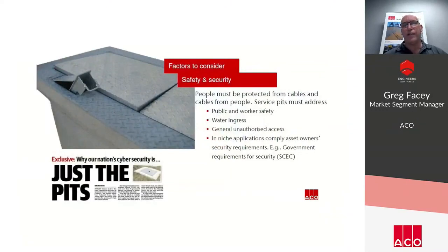We also need to consider the safety and security requirements of the cable enclosure, because people must be protected from cables and cables protected from people. And service pits must address the public and worker safety, water ingress, general unauthorised access, and particularly in these applications to comply with the asset owner's security requirements, so e.g. the government requirements for SCEC pits, because we see heavy security forces in daily events, so it's not hard to